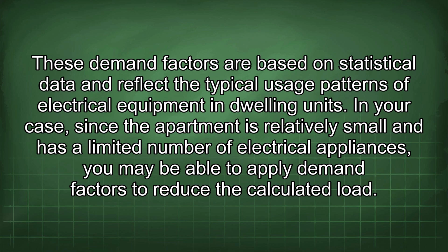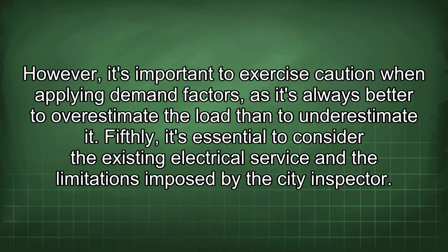In your case, since the apartment is relatively small and has a limited number of electrical appliances, you may be able to apply demand factors to reduce the calculated load. However, it's important to exercise caution when applying demand factors, as it's always better to overestimate the load than to underestimate it.